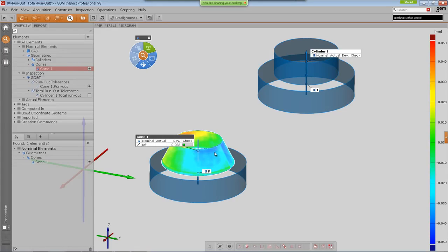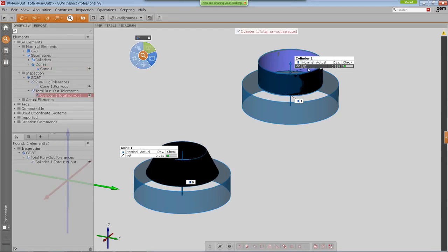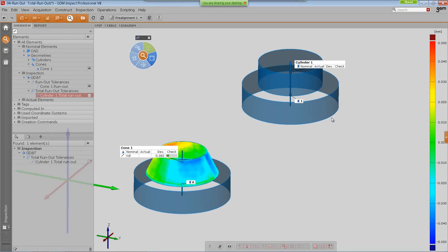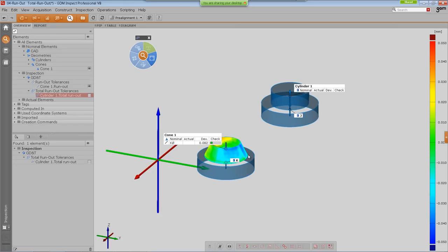and is adjusting the proper legend which you have just chosen for this. This leads, of course, to the fact that if you're displaying two at the same time, which have different legends, we have to do something. So in this case, we won't show any color unless you just change it to a common tolerance zone, or if you just hide one so that there is one legend which represents all the color information which is displayed in the 3D view. Also a small but nice improvement, I think, for dealing with legends and color plots.